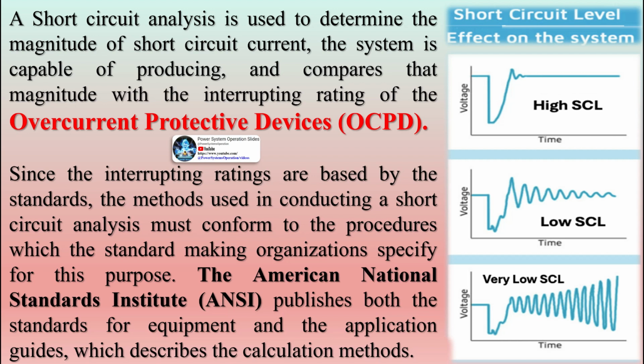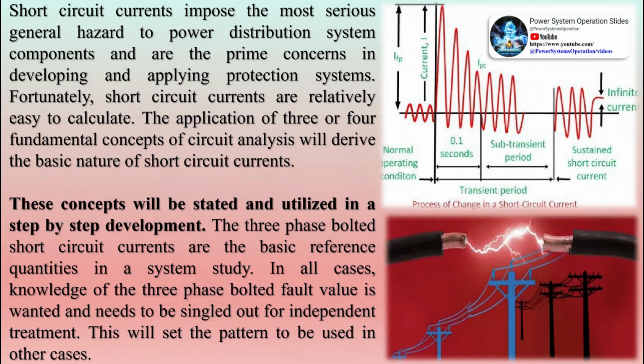Therefore, not only do inverter-based technologies make minimal contribution to system strength, they create additional weakness in the event of a fault. The more inverter-based devices that are connected in close proximity to each other, the greater the system strength needs to be at that location in order to maintain grid stability, as there is a higher potential for them to influence grid voltage.